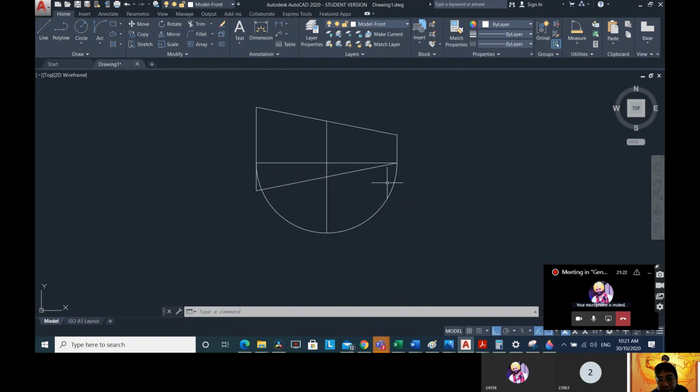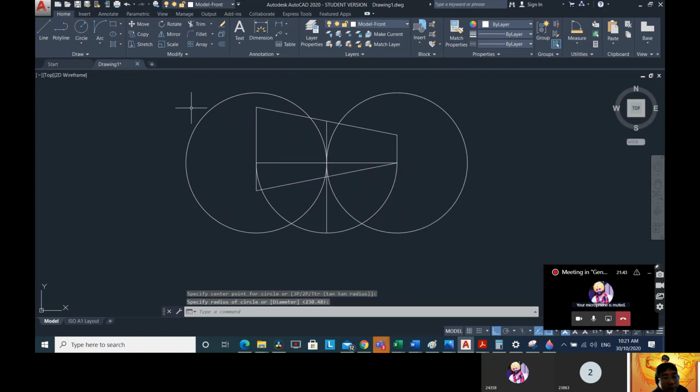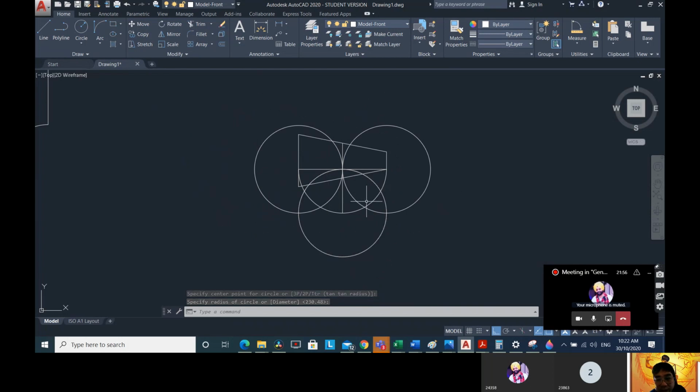I want to develop 6 pieces. So that means the full circle, 12 pieces. So all I need to do is draw 3 circles. From the edge to the middle, from the edge to the middle, and from here to there. Okay, so already I developed 6 pieces.